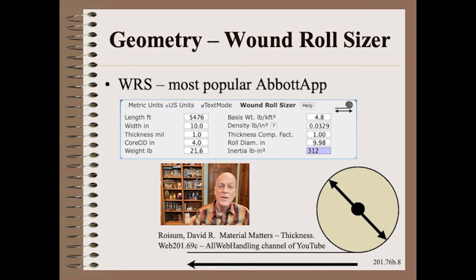Beware, however, that thickness is not a thing that can be uniquely defined or even measured. In-roll thickness is even more complicated because single-ply thickness is different than stack thickness, and stack thickness varies with the radius in the wound roll. How to account for this is discussed in the app and in others of my writings, such as my 2 winding books.